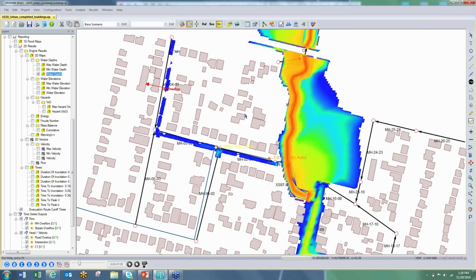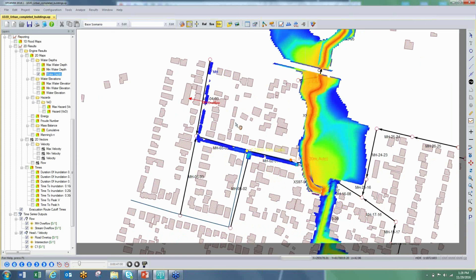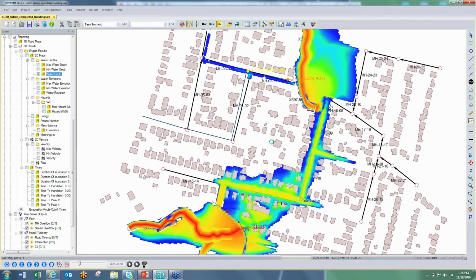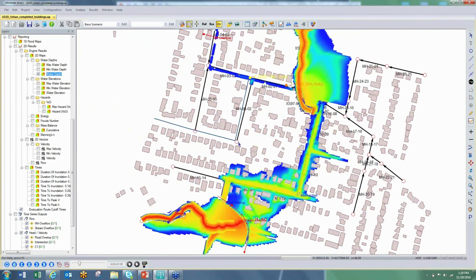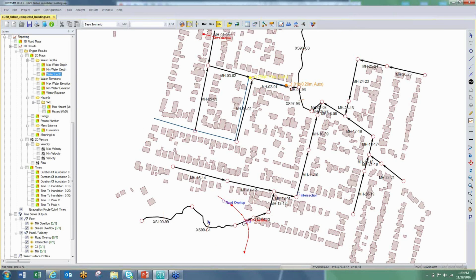Earlier in the model, we talked about the microphones that we put into, I call them microphones or interrogation points, but we talked about the flow boundary and the head boundaries that we put into the model. These are also, I think, useful ways to interrogate the data, especially when we're looking at flood situations. So the flow boundary was this polyline that we draped across this area of the model. So it's going to capture any flow moving from left to right in this instance along this boundary.